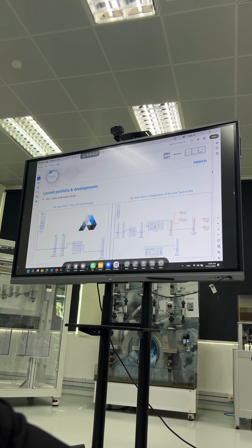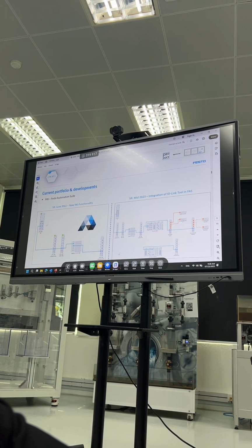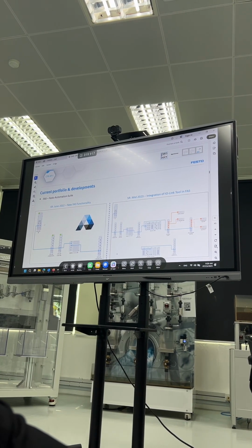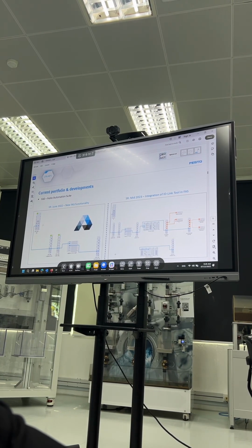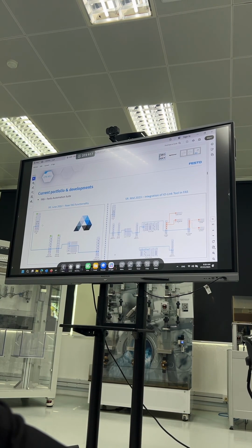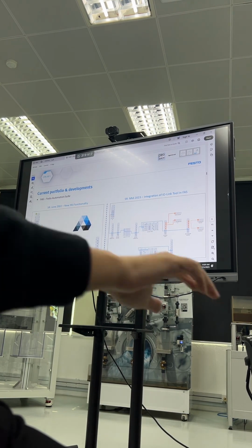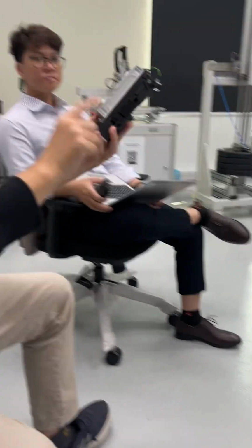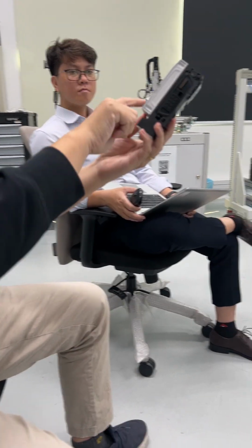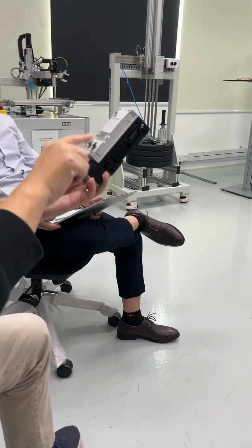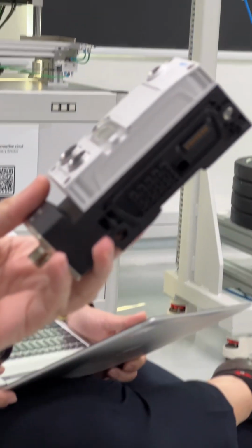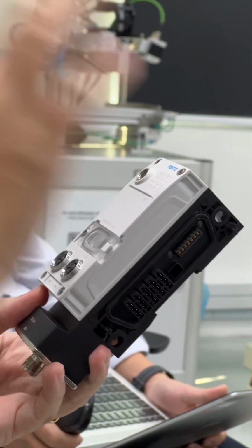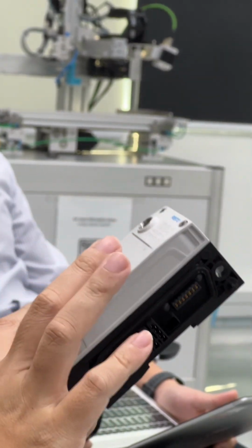But for EtherCAT there is also another way which I briefly told you about last week. Most of our newer EtherCAT modules have something called a backdoor mechanism. Just imagine this is an EtherCAT module. You connect the out port to your laptop, and you will be able to find an IP address for this EtherCAT slave, provided that your EtherCAT is not running.